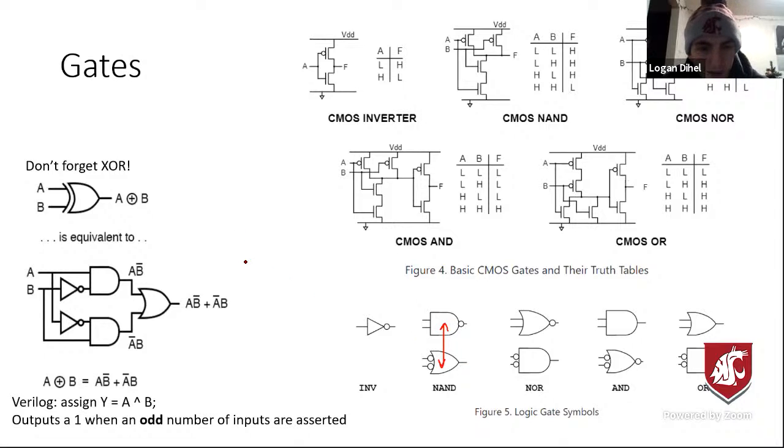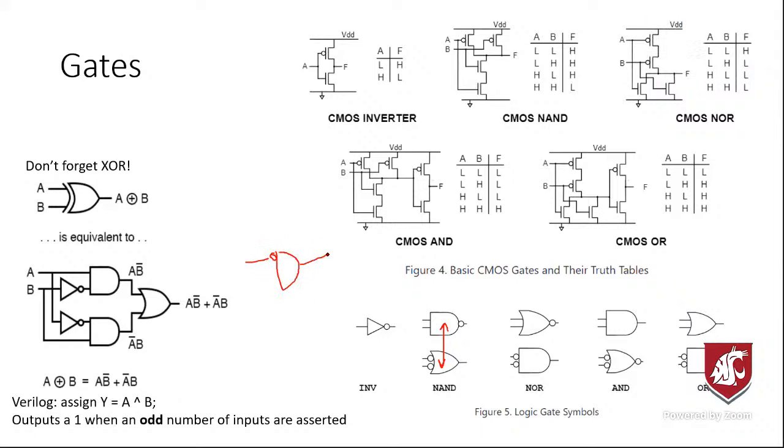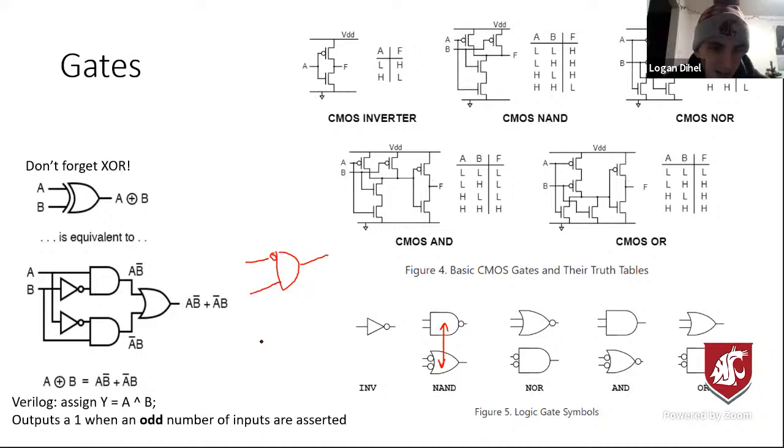In general, if we had a circuit like this, it's the same thing as if we did this. This is an OR gate now. So if there's a bubble, put a wire. If there's a wire, put a bubble, and then switch the shape, and you get the equivalent circuit. All of them use that exact same rule to get between the two.